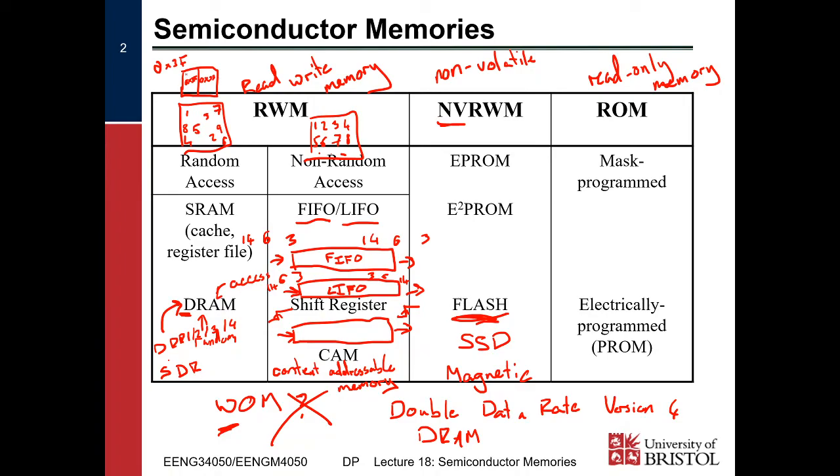The key point here is that if you then try and look up data item 0x1a, 0x1a might be down here, right? It won't be, it's not an offset in the memory, it's an actual data item that you are looking up, right? As a key, and then it returns the corresponding value. Maybe 0x1a has a value of 0x0 associated with it. Okay, so it's a key value storage, and so you can't just randomly access it. You need to know an item that is in the content addressable memory and then query the corresponding value, right?